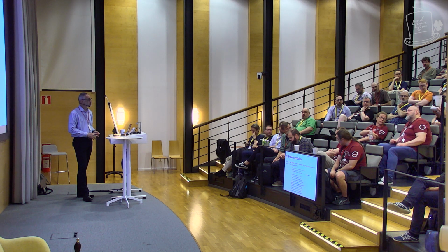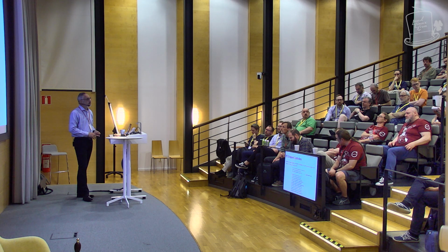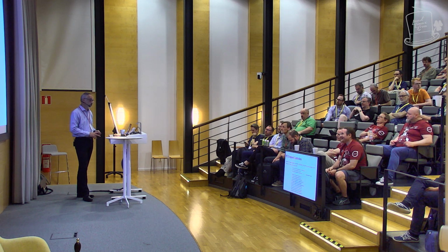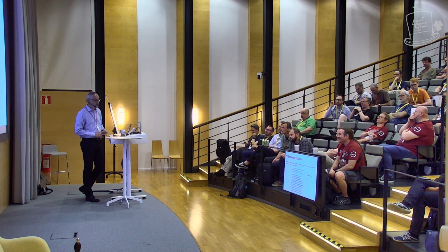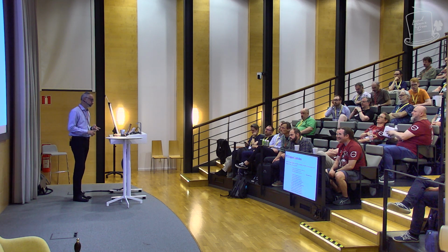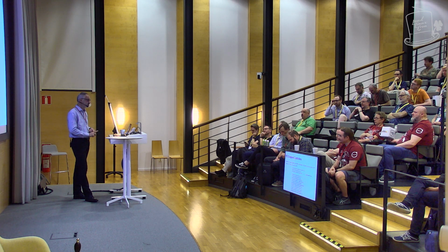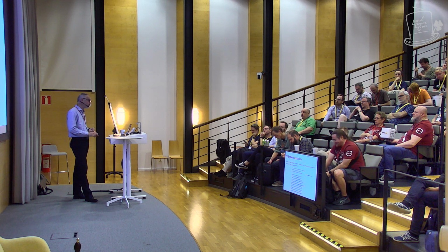Now, when you were looking into all those, have you been looking into the Jetson from NVIDIA also when you investigated, because they have a bit more performance, PCI Gen 4, and now they have the Jetpack 6 upstream? Yes. I did look at all the boards that we could find that had endpoint, and Jetson was there, yes. Just more expensive, harder to procure, that's all. So we just went for the simplest one. The upstream support also not great. You have to use out-of-tree stuff, from what I remember. Maybe it improved, but at the time when we started that, more than a year ago, it was still a lot of out-of-tree things that we really wanted to avoid.